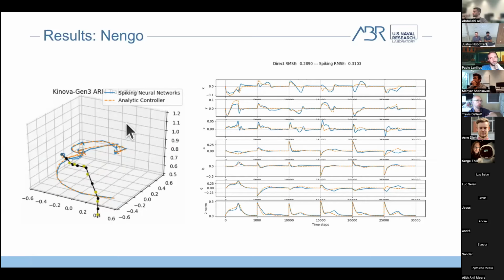Yeah, so what we're doing is we're doing PID control in task space, and then we're transforming that into joint space using the Jacobian and the inertia matrices. So the inertia matrices are kind of used to linearize the control of each of the joints, and so you don't have to worry about the Coriolis or inertia effects from any of the other arm segments. And the Jacobian transforms us from end effector forces into joint torques. Thanks.